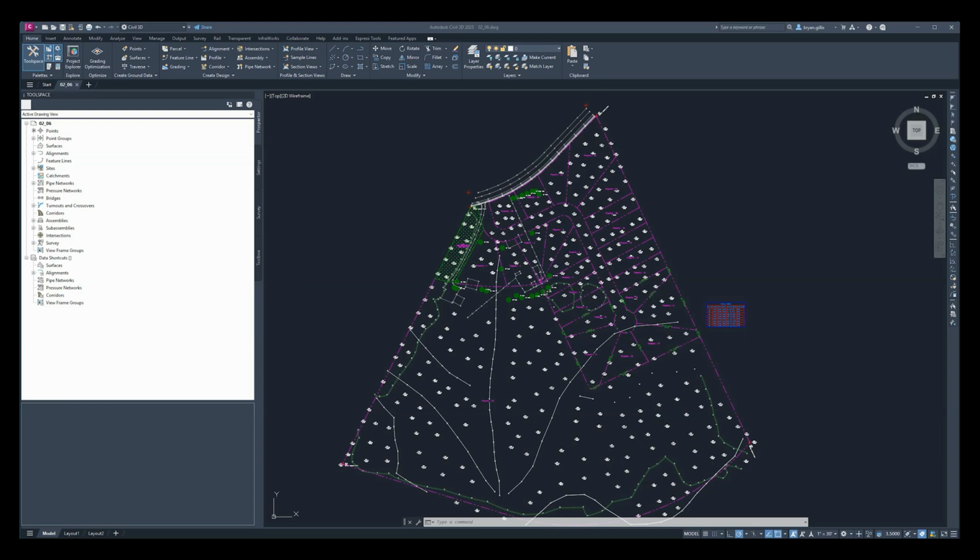up surface triangulation. So in Surface 3D, to create TIN lines, what we're going to do is connect our surface points that are closest together. And the elevation of any point in the surface is going to be defined by interpolating the elevations of the vertices of the triangles that the point lies within.